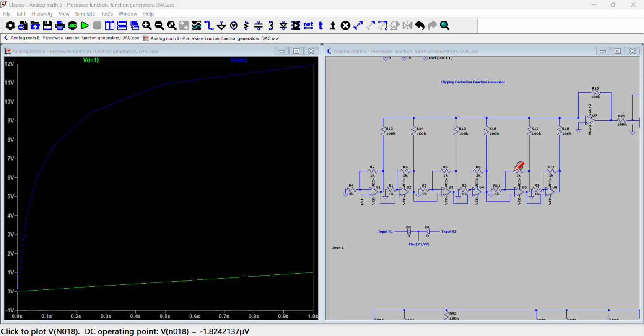For example, if you look at what's happening within any particular gain stage, it's essentially running a minimum function. It's basically calling the min math function, and the two input values are the rail voltage and the output amplified voltage.